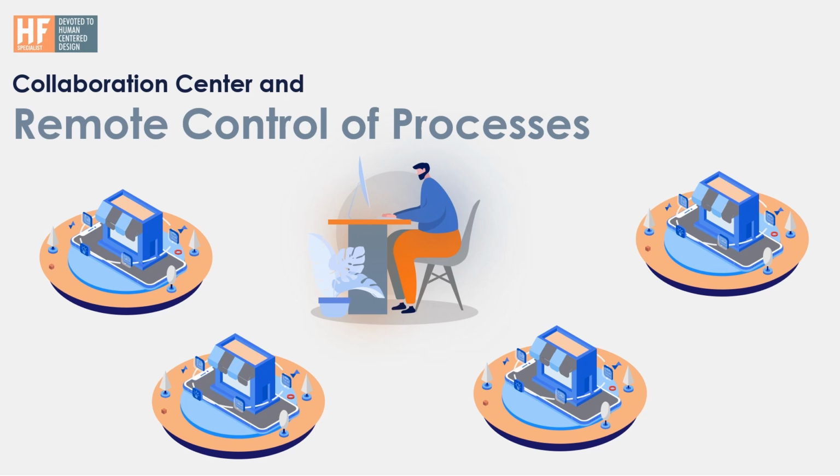But at the same time, you should identify the risks so you don't build latent risks into the control center, and you can avoid that by identifying the functions, to see what the critical functions are that you have to address, and make a risk assessment and see the impact of it, and how you should solve those problems that may occur if you're sitting at the control center, because you are not going to be near the process, and you are not going to have the tacit knowledge, in the form of sound, smell, or vibration near the process that you usually have.